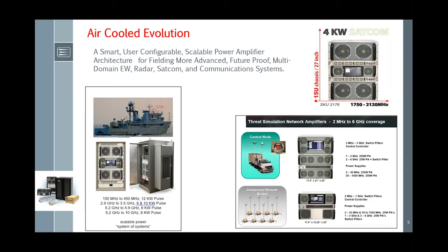George, what do you mean by long pulse width and duty cycle? What is unique about that performance? Well, first of all, it's difficult to do in a TWT. So the TWTs that are available don't offer that. In solid state, we're uniquely positioned. Paolo could probably explain what it is that we do differently, but I'm talking 20% duty cycles, for example. That's what I mean by long pulse. 20% duty cycle, and 550 microseconds pulse width. Okay, got it.